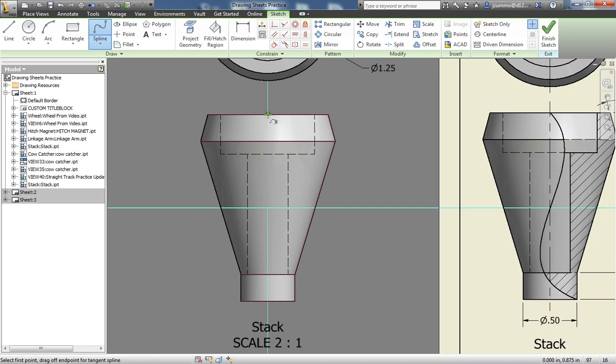So I'm going to click once, left click once, and as you drag out here, you can see I have a line. I will then, in this area around here, left click a second time, and you can see it then begins to bend the part, and I have this option for a green check mark. This option will continue to follow me as I left click at more intervals here and increase this spline.